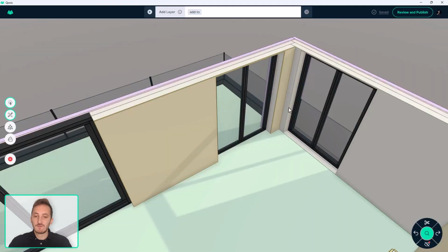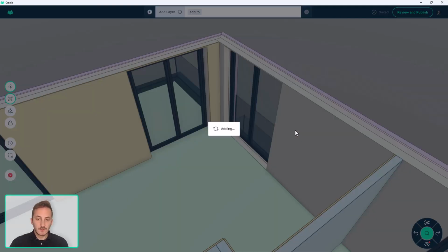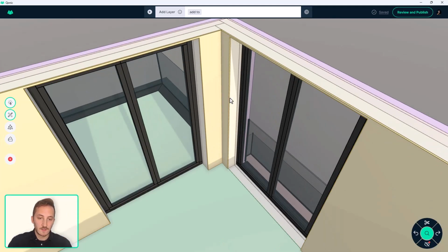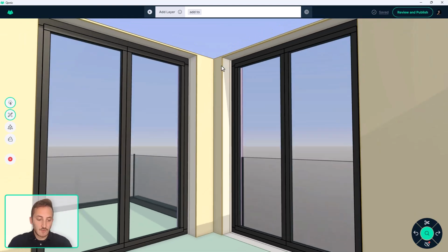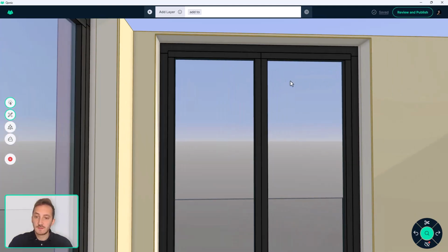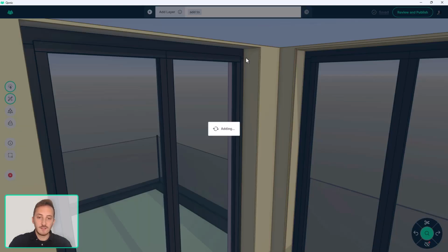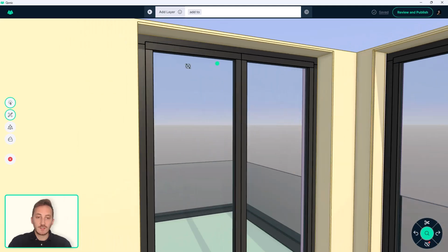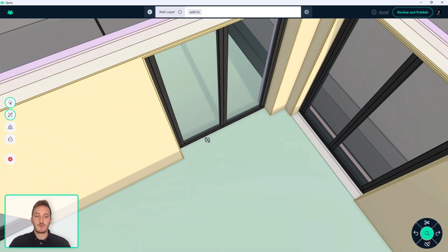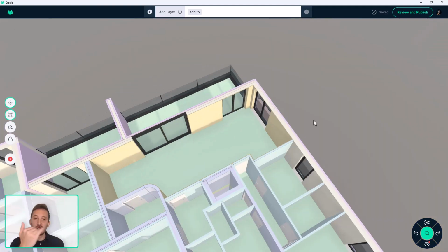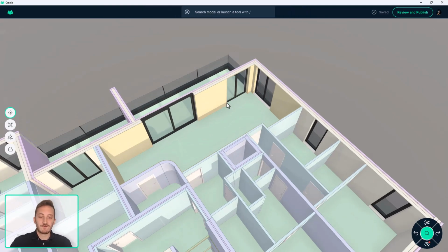Of course, also in a future version, it will be possible to assign finishing layers to entire rooms at once, or to types of rooms, for instance. But this flexible approach allows you to also model, for instance, the inside finishes of window openings. So you have a really flexible way of modeling these details, which in a later stage will become important if you want to, for instance, get a quantity takeoff of your model. All of these extra finishes that you add in the inside of the windows will make a big difference in the final quantity takeoff.